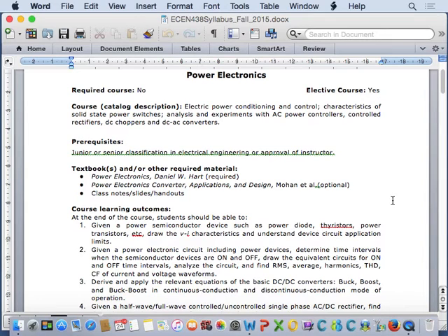Where do you want to send that? You want to send that to people's homes, or you want to send that into the grid, right, to supplement the grid. The grid voltage is what? A fixed voltage, quote unquote fixed, because when you study power systems, if you studied the 459 course or the 460 course, you know that the power system voltage is not fixed voltage all the time. There is a variation in the control system behind this whole power system. But for the most part, it's a fixed value of voltage and a pretty fixed value of frequency.